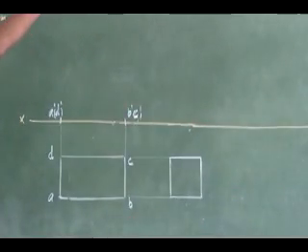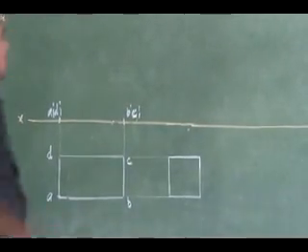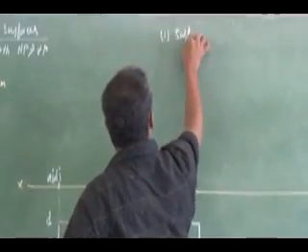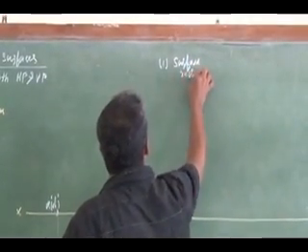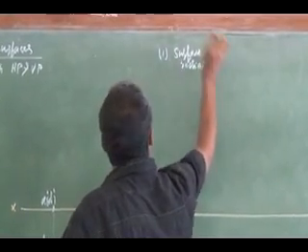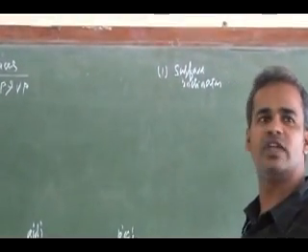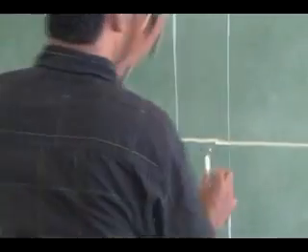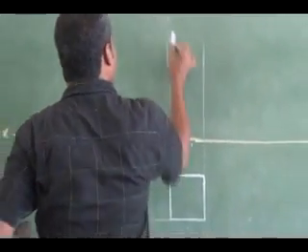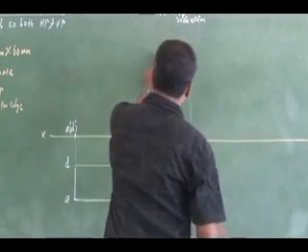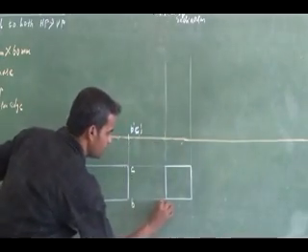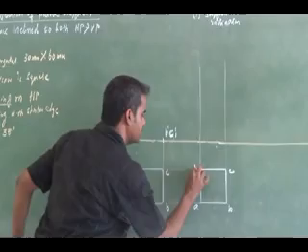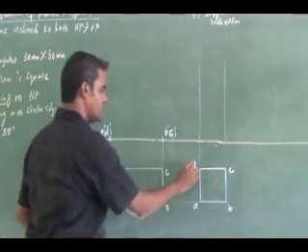Now, how can I find out the surface inclination? I have to project it. Here I could use a surface inclination as in the previous problem, but I have to find out the surface inclination here. I know the top view here. So I can extend the projectors and draw the vertical projectors. This is going to be my A. D. Now this is a square, you know.